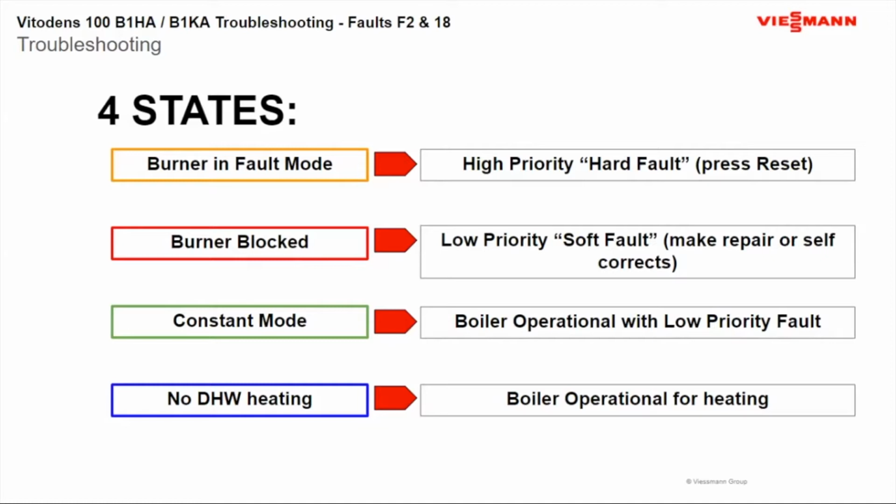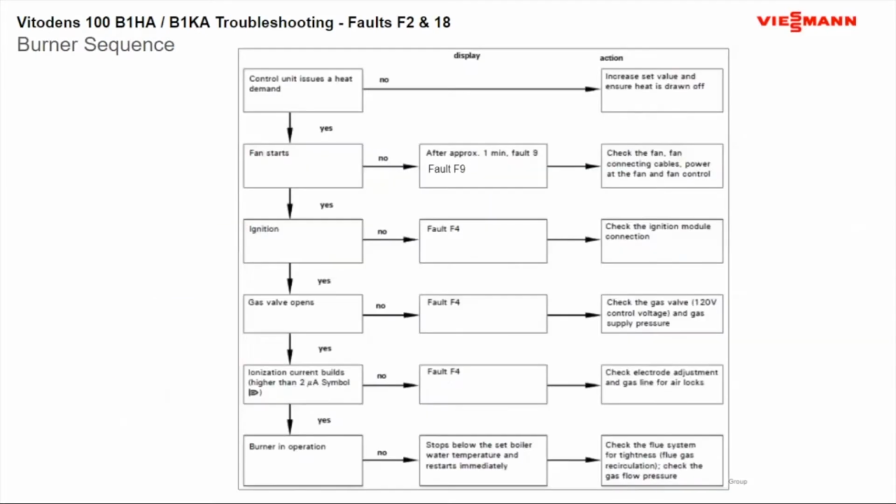And that's what I noticed with this boiler. As soon as you power the boiler on and off, it automatically gets rid of that outdoor sensor and continues to run. But just be aware that our boiler does come defaulted for a fixed temperature at 158. So you will want to increase that if you're running any high temperatures. You might not have domestic, but you could still have heat as well.